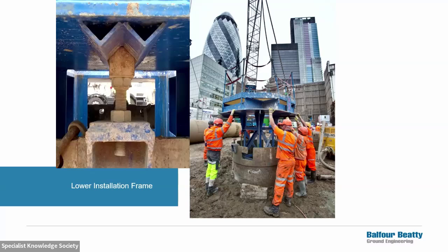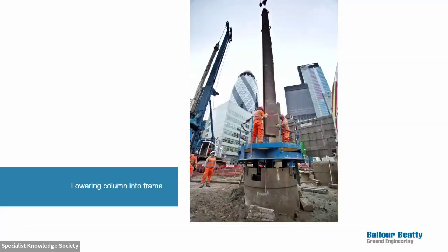And the frame can be put into quite a tight tolerance, so you can ensure your structural element, your plunge column, is lowered into that frame to keep it at quite a tight tolerance. You can see that plunge columns can be quite big, they can be quite hefty. Obviously they've got gravity which helps them be vertical, but plunging them through that frame down into the open bore of the pile, and then down into the concrete at depth to support them, and then they're held in position with that frame until the concrete's gone off, and then the frame can be lifted away.